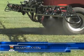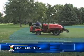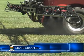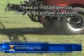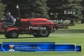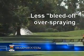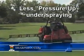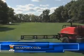SharpShooter controls the on and off spraying function right at the tip, and shut-off is instantaneous. The liquid and pressure are retained at the tips, so when the boom is turned on, there's instantaneous flow at the proper pressure. That makes starting and ending an application pass easy, immediate, and precise. The quality opportunity amounts to less bleed-off overspraying of chemical when the boom is turned off. Likewise, there's less pressure-up underspraying that results in several feet of under-application when turning the boom on again.